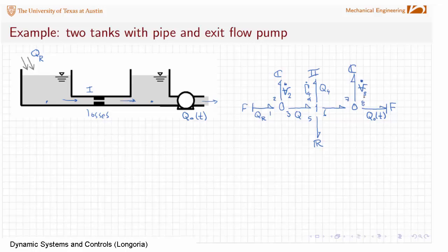So now I start looking for other sources. I don't have any, and now I can look at my 3 energy storage elements. And since I have a C here, I'm going to start with that one, and I want integral causality. And what is integral causality? I have flow in, so let's assign flow in here, which means this is independent.